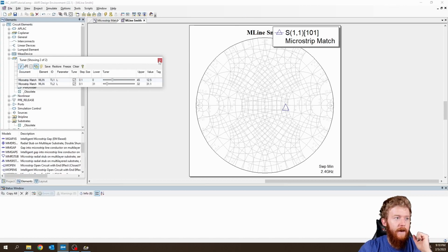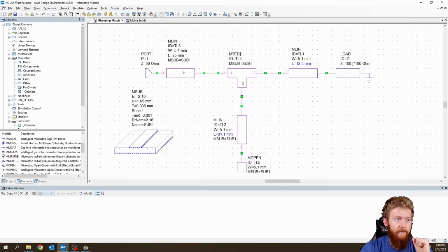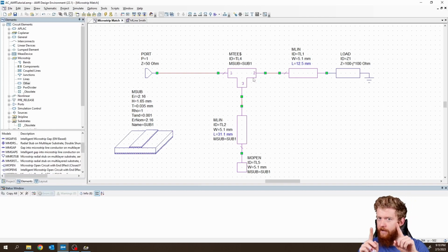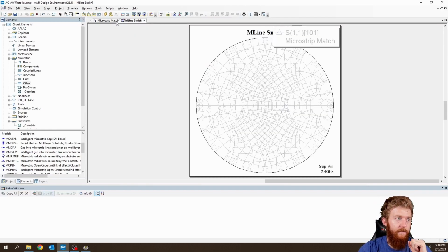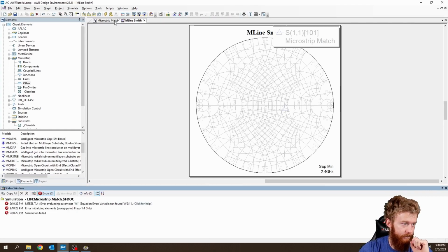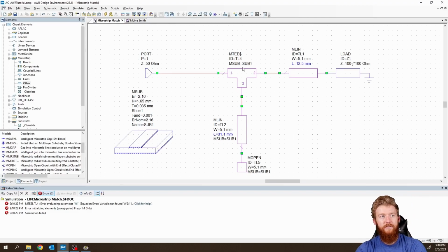Because we have this long strip of transmission line, we don't exactly see the input impedance here, which is tough. But like you said, having this junction here adds a little bit of extra transmission line anyway, which adds some delay. So let's go ahead and get rid of that long one. Maybe make it a little bit closer to reality. Uh-oh, variable not found. Oops. Okay, like you said, this one, even though it's intelligent, if it's not well defined, it's going to be a little bit tougher.